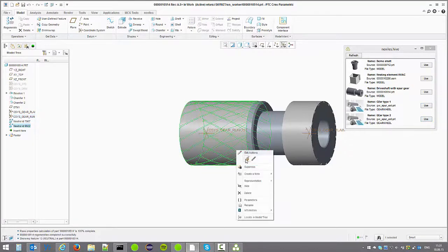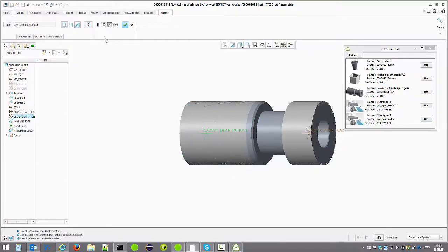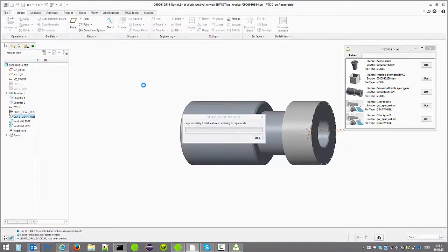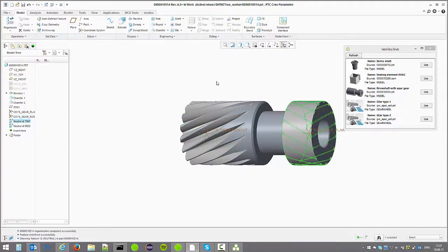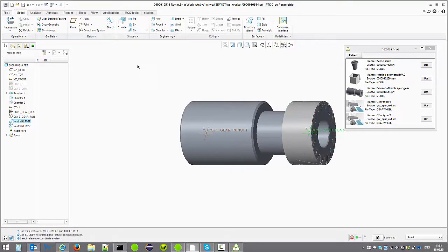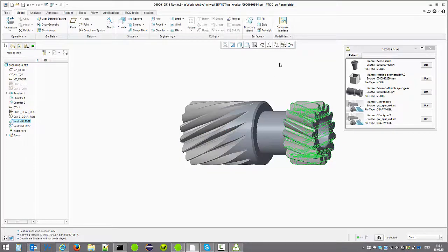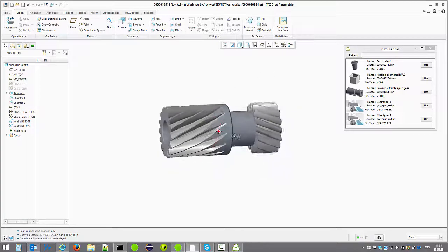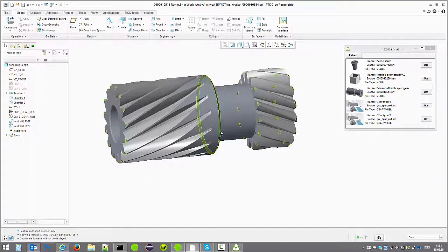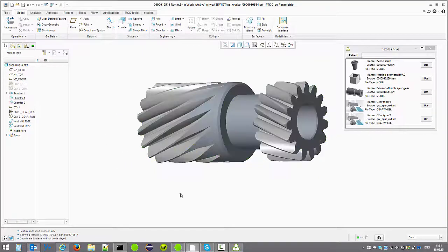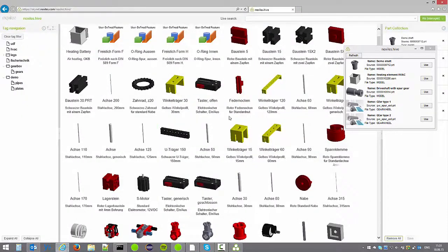What I need to do is just use this surface model and say to remove solid material, and the resulting geometry is the actual gear geometry. So now you can see with the second one we have two different types of gears applied to the shaft, and the gears are according to the specifications as we have specified for the template.